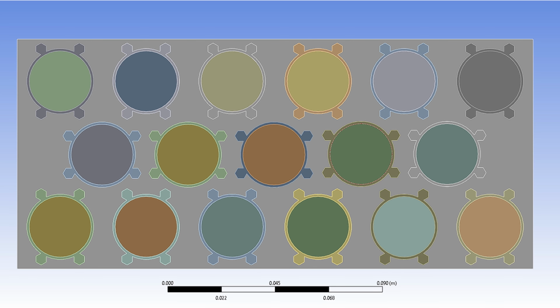So around the cells, as we are observing in the earlier image, we are having a kind of casing, and around the casing there will be a fins kind of arrangement which is provided. So this is a kind of hexagonal element. Each side has 2.5 mm thickness, and from the center to the center of this hexagonal portion, the distance is 16 mm. So accordingly we are proceeding for the simulation part.